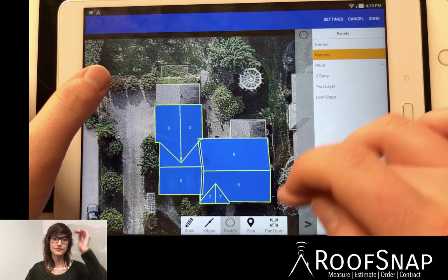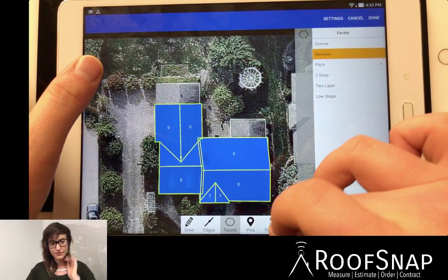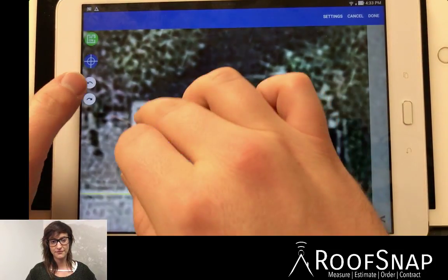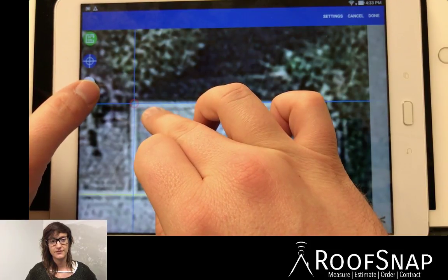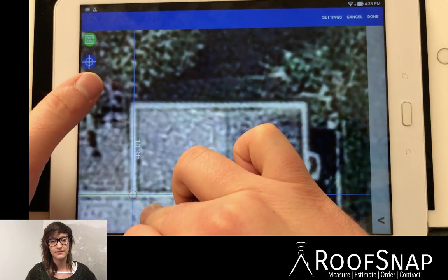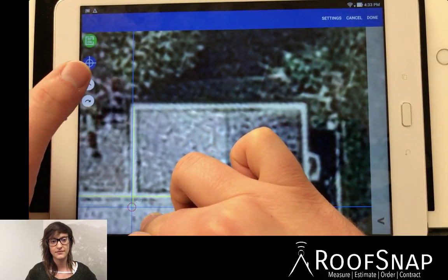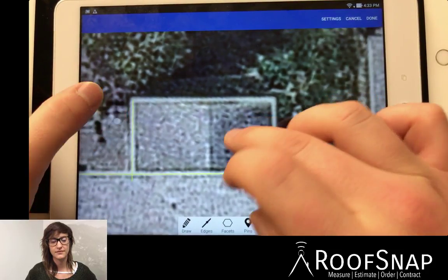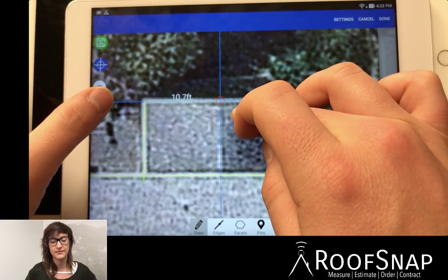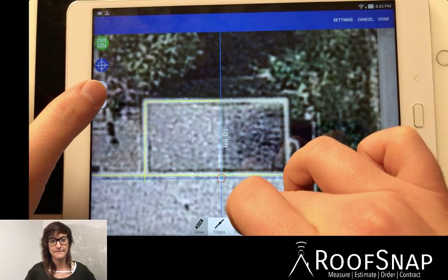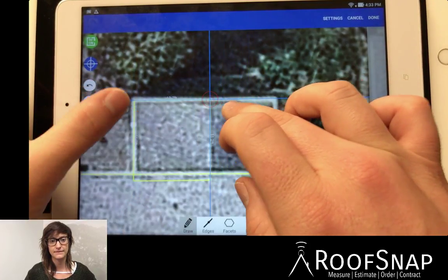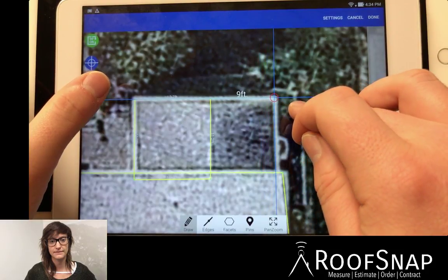Okay, now the last bit that we need to do is finish out the rest of the drawing with proper overhangs. And you may have seen us draw this roof in the past in our dormers and overhangs video. So here, I'm going to draw down at the eave edge, but I'm going to continue past about a foot. Now we can draw the rake up and stop at the ridge. Always stop at the ridge and draw those ridges in. Don't do one continuous line for up and back down a rake. Two separate lines for each side of a gable.